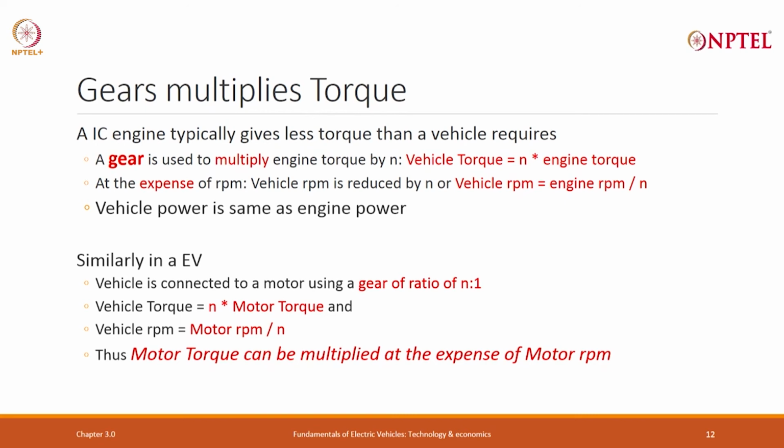Well, there is always a gearbox efficiency, which I have not taken into account, and which I will leave to the motor people. EVs normally use a single gear, n is to 1. As was pointed out, there is a certain efficiency, which can be 98%. So, very close to 1, we normally will assume 1 unless it is required. If there are multiple gears, the efficiency gets worse. A single gear is kind of almost fully attached, and you can get very high efficiency, 0.99, close to that.